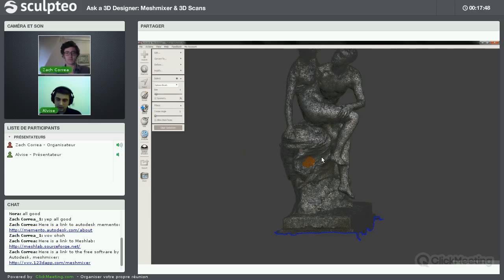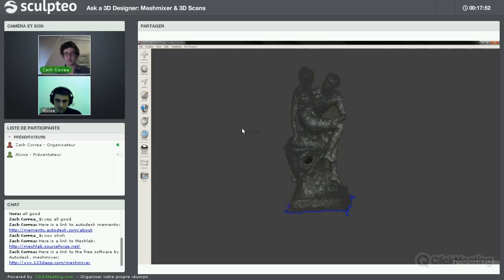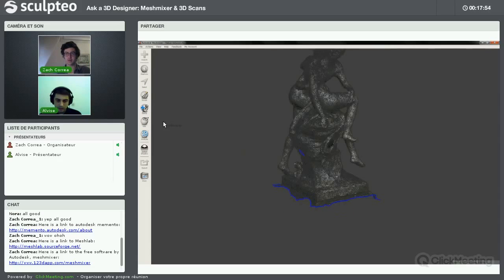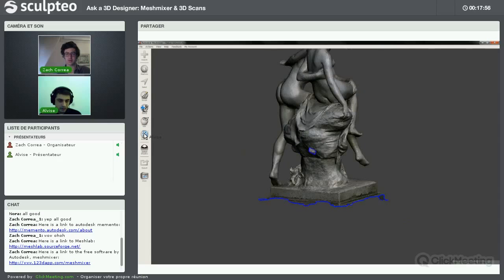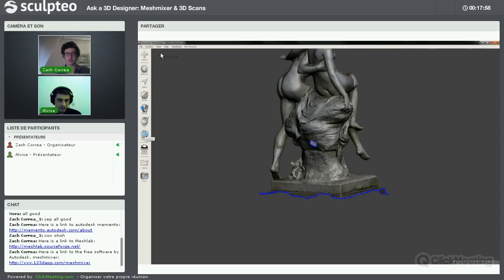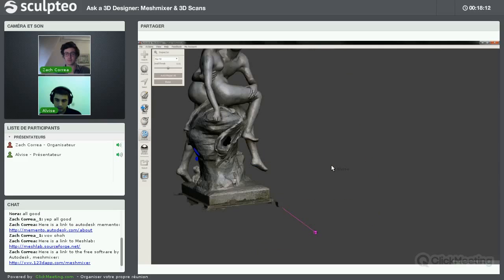Once the colors update, we can come back to the shader, normal shading, and try to close the second hole. For this one, I'm going to show you another way. Go to the Analysis tab and click on this very useful tool called Inspector. When Inspector is selected, these balls appear showing you the problems that the mesh currently has.